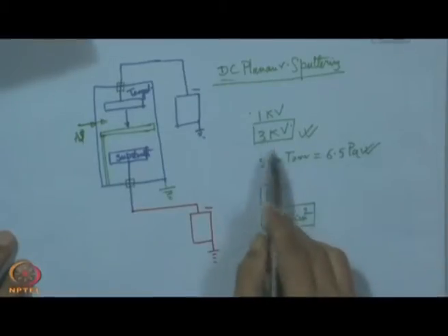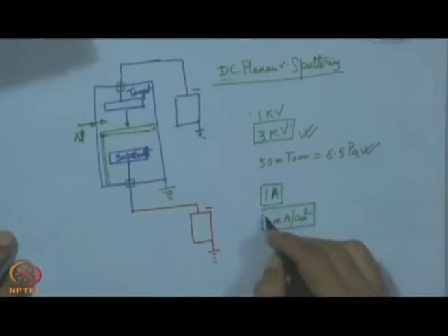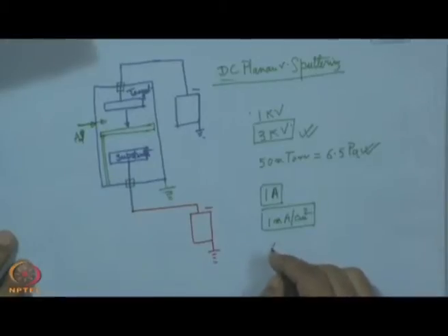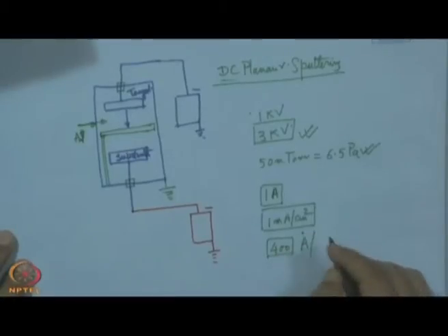So, even with the best effort, what we can see is that this is just the order of ion current density and sputtering rate, that will be maybe around, say this is just an indicative 400 Angstrom per minute. So, that may be one of the indicative values for this.